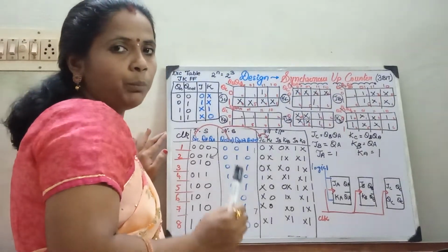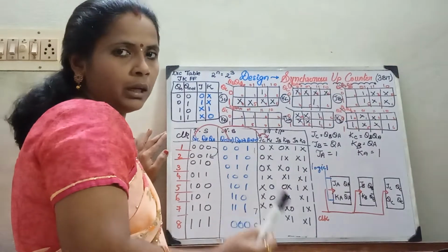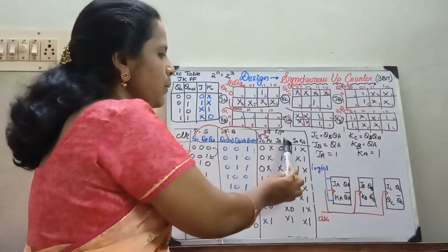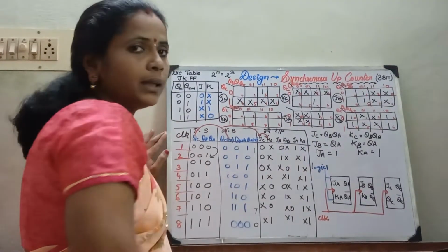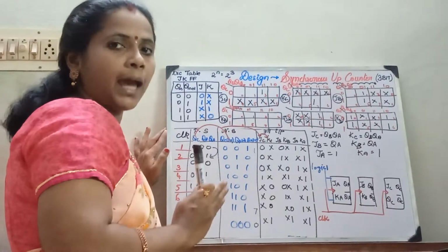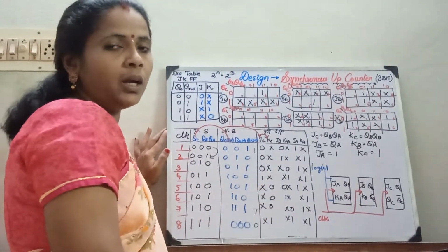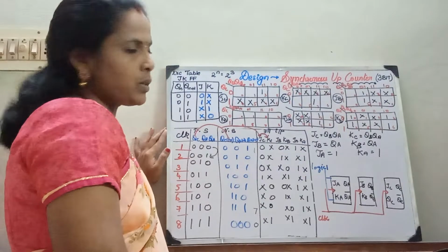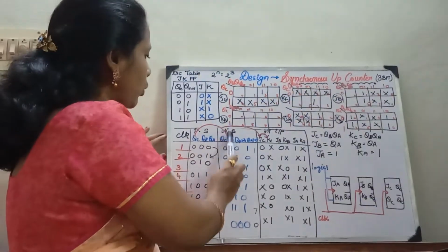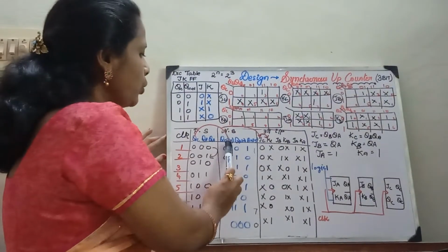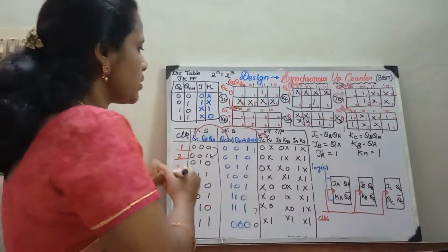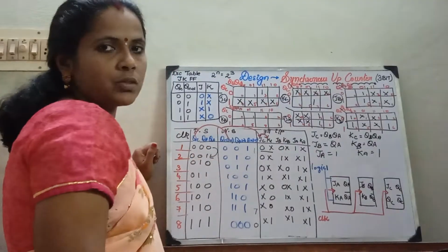You have to compute the input data, what you have to give to your flip-flop for designing it. So you have 3 flip-flops, so JC, KC, JB, KB, JA, KA are the inputs. Now what is the excitation table? Knowing your present state and the next state, you compute the transition between the inputs, right? So now my present state QC is 0. You can just see this arrow mark. QC next state is 0. So for the 0, 0 condition, what is the value? 0x. So just write it here, 0x.